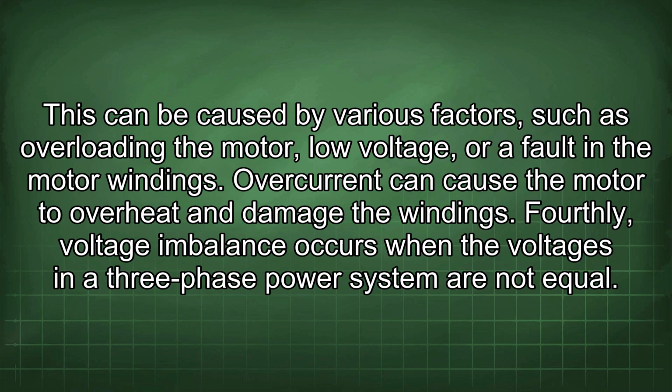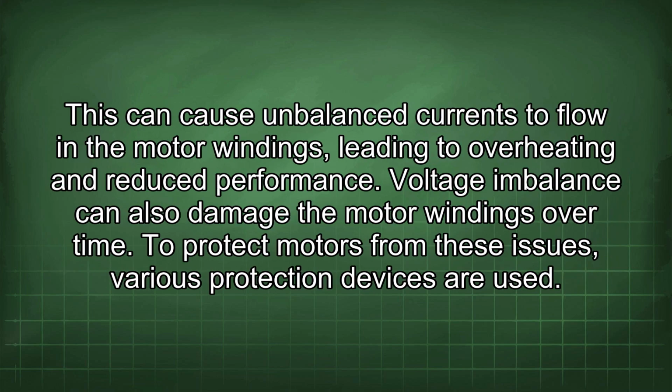Overcurrent can cause the motor to overheat and damage the windings. Fourthly, voltage imbalance occurs when the voltages in a three-phase power system are not equal. This can cause unbalanced currents to flow in the motor windings, leading to overheating and reduced performance. Voltage imbalance can also damage the motor windings over time.